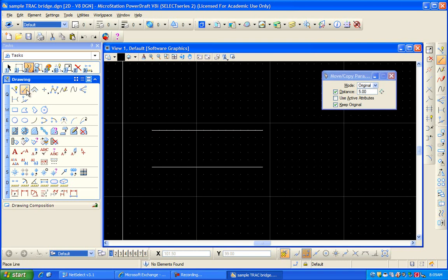I'm going to click on the place line, and I want to offset a line 4 inches on either side, which will give me 8 off the midpoint. And to do that, I'm going to check down to my snap tools, which I said are important for drawing things out right, and I'm going to make sure I have the midpoint snap on.